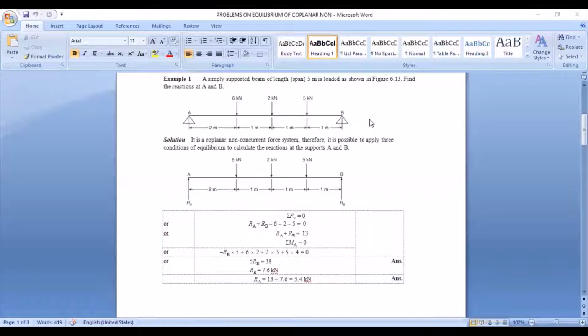And we all know that a free body diagram consists of self-weight, actions, and reactions. But in this case, as we have discussed, we are not going to have the self-weight of the beam. So that is neglected. So basically, we are going to have only two terms, that is actions and reactions. Now, actions are those which are externally acting on the beam. So we can see that there is a beam AB with three point loads acting on it. So basically we have three actions.